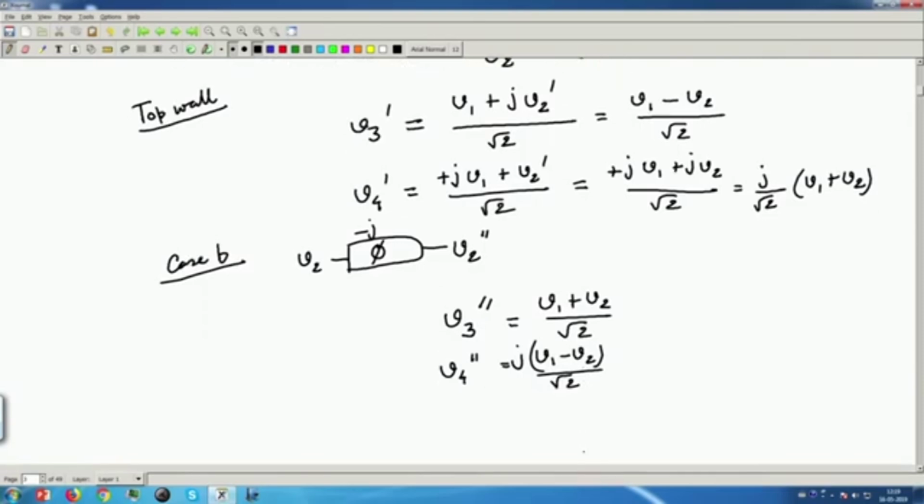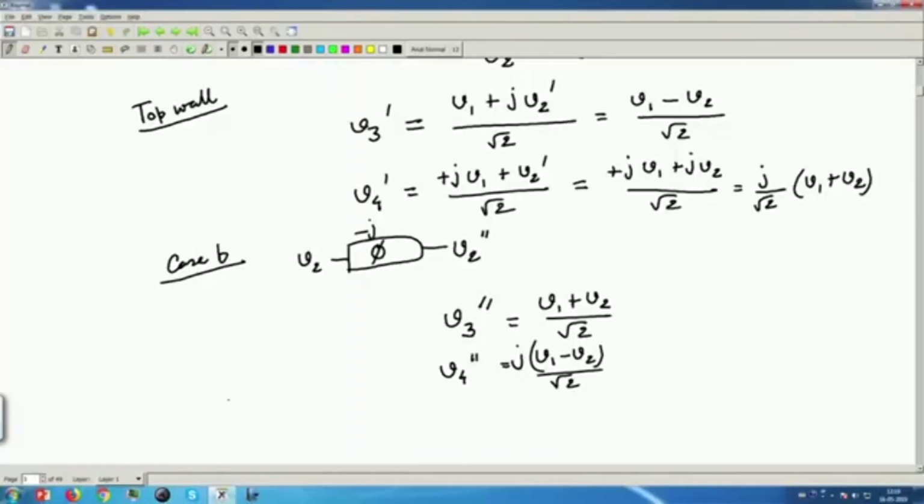So, in the directional coupler we can have that, and the directional coupler does not have, like the magic T, any different horizontal and vertical planes. So, it is easier to construct. You can have planar structures of this also. So, this coupler is called a quadrature phase coupler, and it has various names.